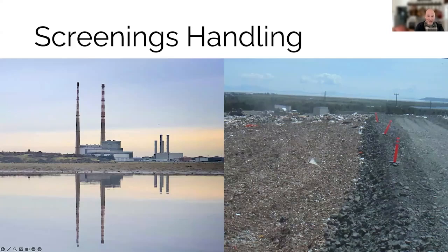Obviously, we've been talking about taking trash out in a variety of different ways. Ultimately, you have to dispose of that. And the screening process can actually generate quite a lot of material. You're going to get anywhere from probably 1.5 to 8 cubic feet of screenings for every 1,000,000 gallons of water that you treat, depending on the screen size. Obviously, the smaller the openings, the more stuff you're going to catch. Those screenings have to be dewatered. They have to be disposed of.